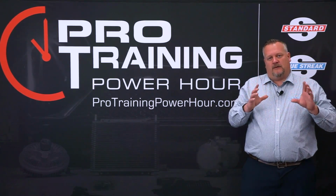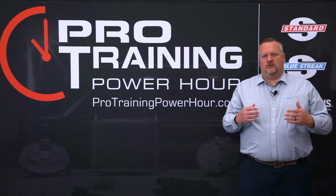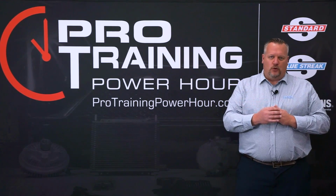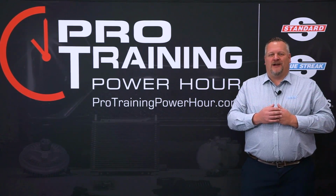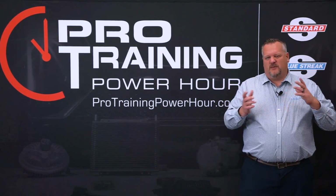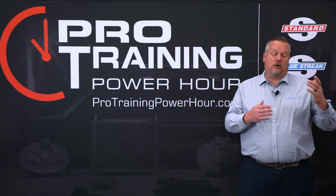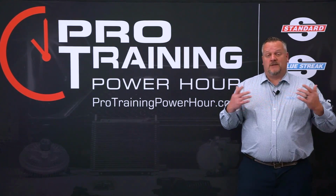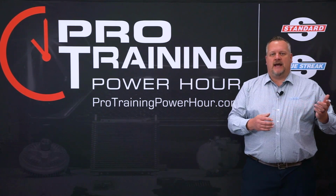Today I'm going to talk about fuel injection, but in a little different manner. I'm going to focus on diagnosing fuel issues or input issues or air-fuel ratio issues, specifically using fuel trims. Now fuel trims has been around for a long time. Back when I started working on cars in the GM world, we called it block learn integrator, and there are some different terms, but it's the adaptation that the engine control module or the powertrain control module makes based on corrections to the air-fuel mixture. So let's take a look at how things have adapted through the years and how we can use it to our diagnostic advantage.